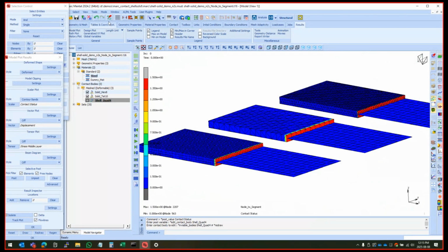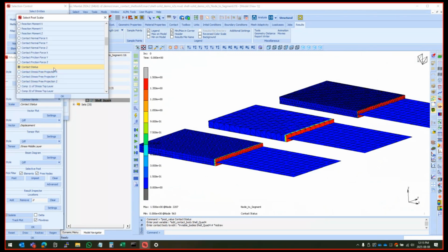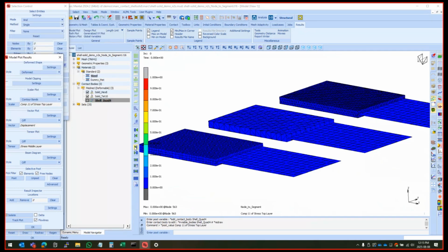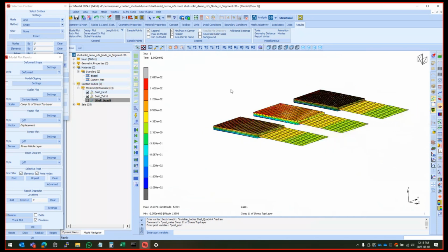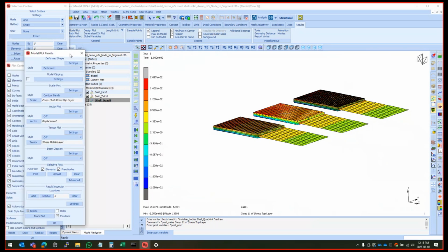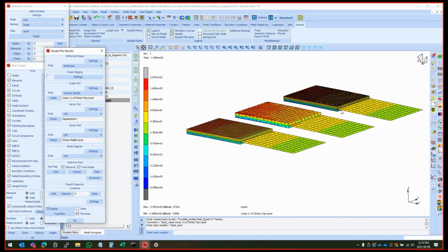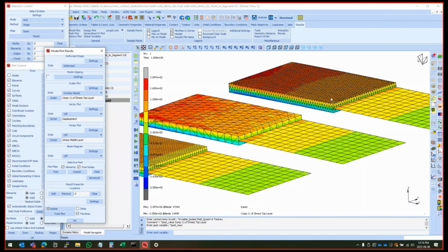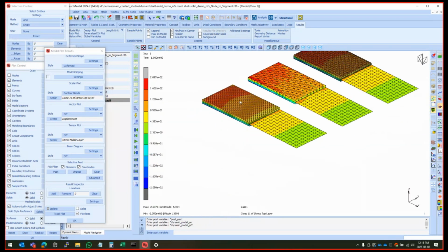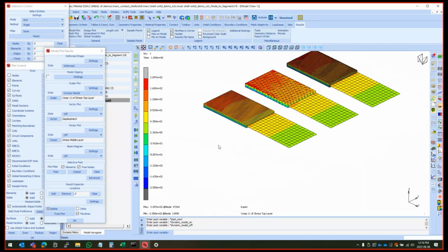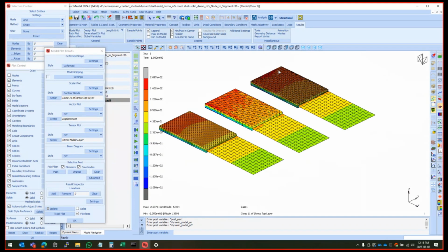In terms of the result for this one now, I can plot the component 1,1 of stress. So that's again the X component of stress. And this is now, I didn't change anything on the scale. So the scale, you can see that it's set to whatever the actual default is. So instead of that insanely high stress with really weird stresses over there, it kind of makes sense. Yes, the pattern doesn't make too much sense yet, but again, I didn't bother getting a perfect mesh.